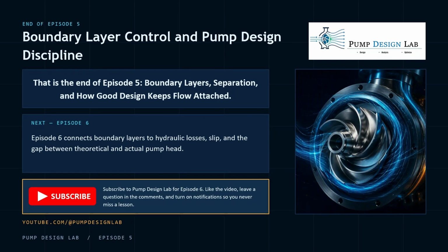Remember the main message. Boundary layers are thin regions near walls where friction slows the fluid. If the slow near-wall fluid faces too strong a pressure rise, it separates. Good pump design protects the flow by keeping pressure recovery gradual and by maintaining enough momentum close to the wall.